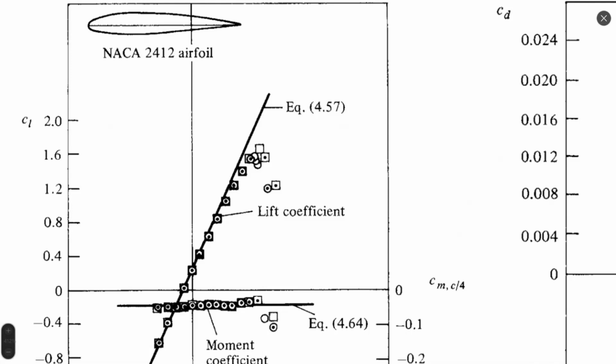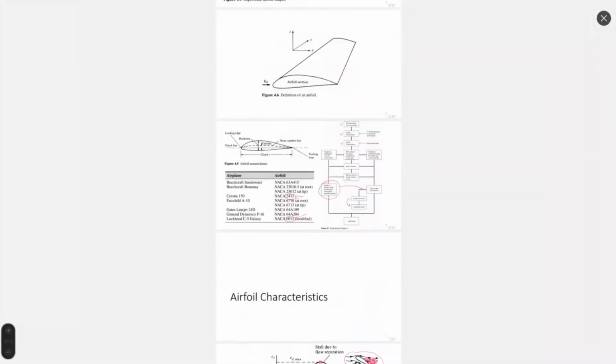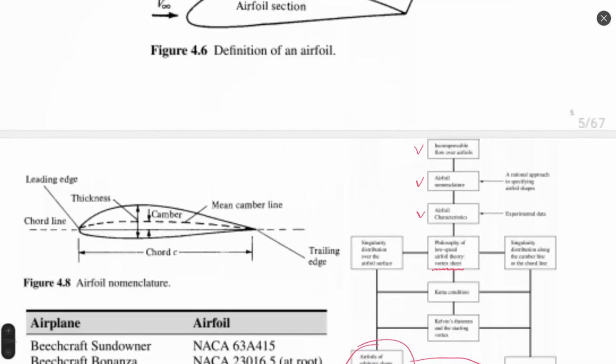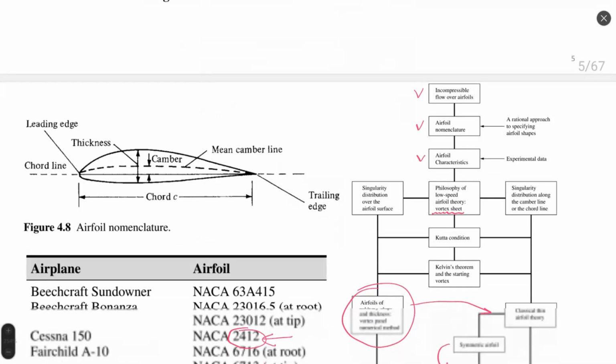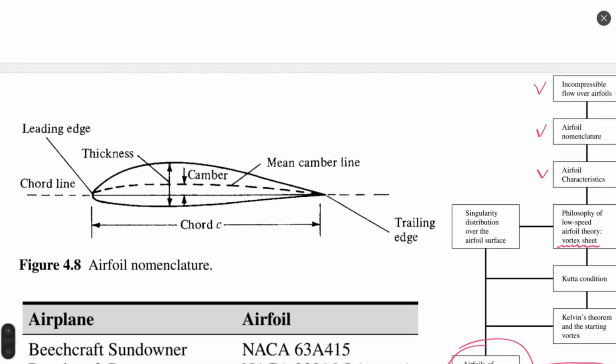No, not at all. I might have used the wrong term. The central line of the airfoil is dislocated upwards. Like with the 6409, I think, the airfoil that I'm analyzing. So it is a thin airfoil, but it is not a case like a flat plate, because the geometry is going first upwards and then going back down.